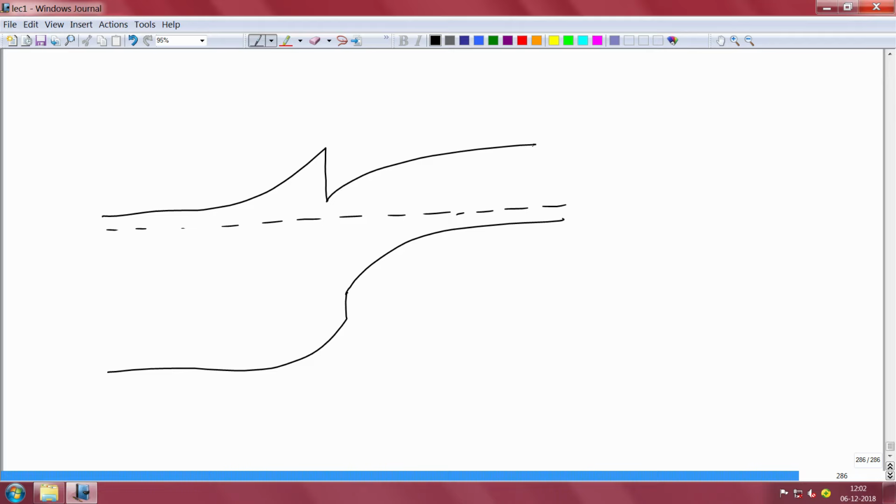Okay. So this is the band gap on the p side, I'll call it Eg small p. That's okay. So you see, if I start from this Fermi level, this point, suppose I go up by this quantity. What is that quantity? That is Ec minus Ef on the n side, right, which is very easy to find out if you know the doping, by the way, using Maxwell-Boltzmann.